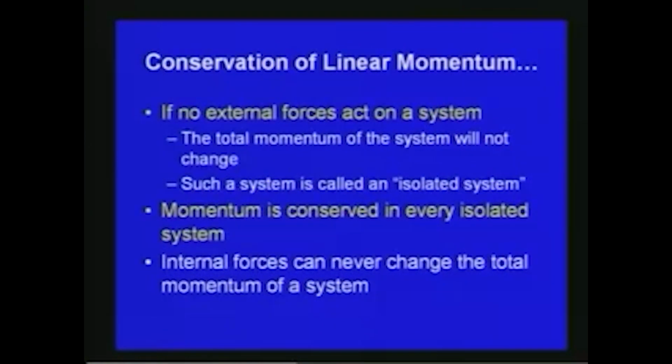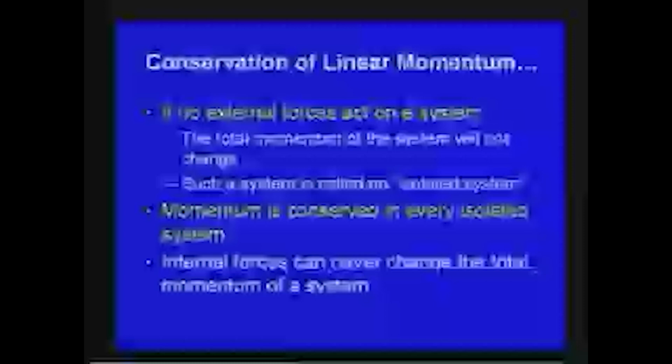So the system can be of two types. In one, the total momentum of the system is not changing, there is no external force, and the fluid or the body is moving with its own initial momentum, so the total momentum is not changing. Such a system is called an isolated system. The other type of system is where we exert a force, so there is an impulse and a change in momentum. When we consider the dynamics of fluid flow, most of the time we will be discussing external forces acting on the system, but sometimes, depending upon the problem, an isolated system will also be considered.